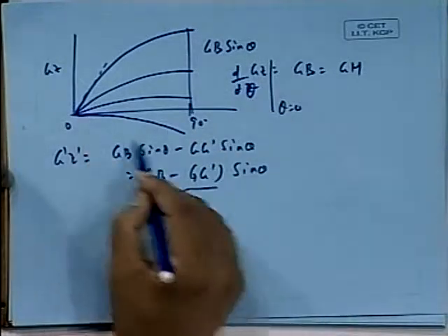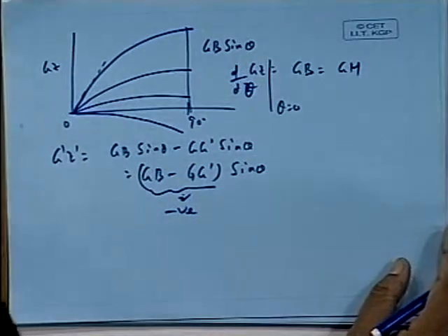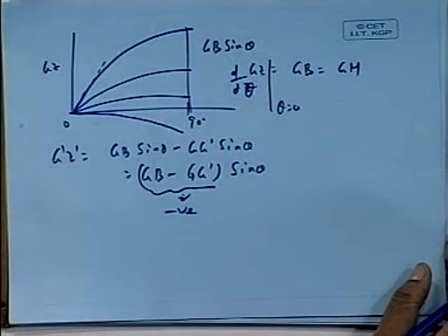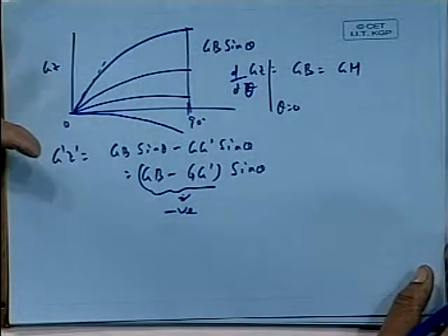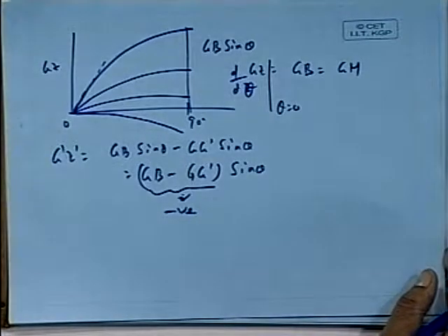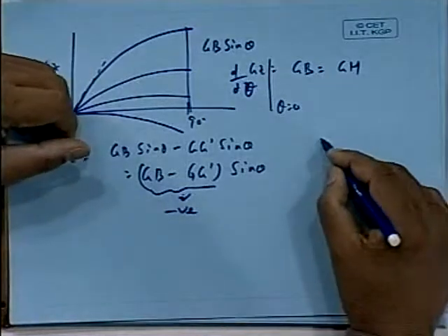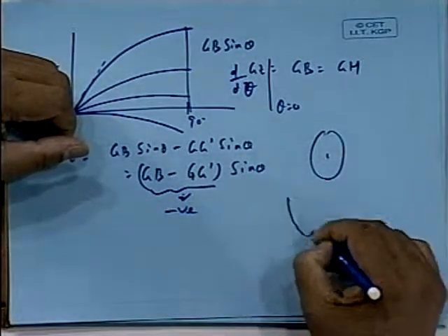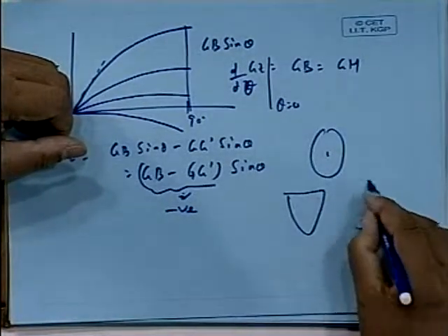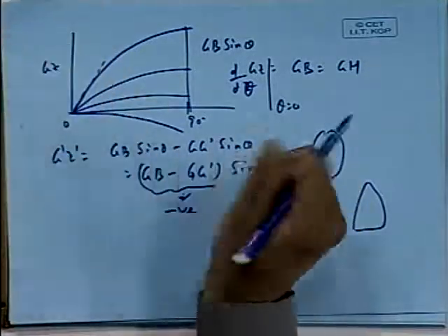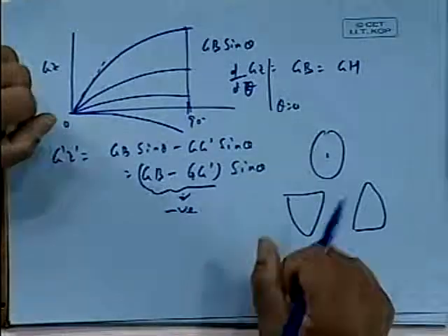So for this fully submerged condition, either the shape is stable or unstable. There is nothing like a range of stability where it is stable for 0 to 10 degrees and then unstable. Either it is this way, or it is this way, as simple as that. If it is unstable, it will simply turn turtle and go upside down. There is no in-between position you can have.